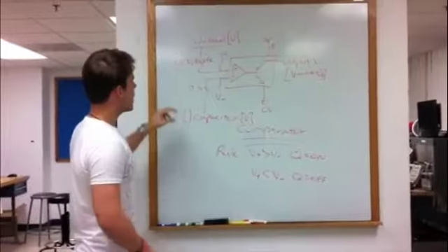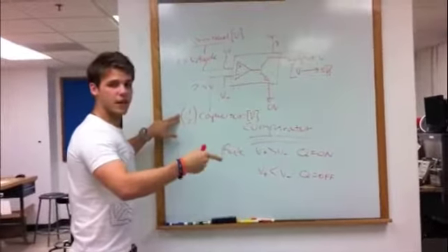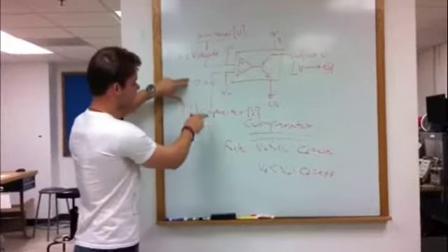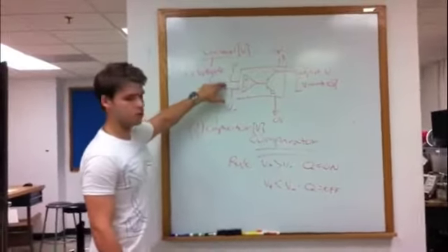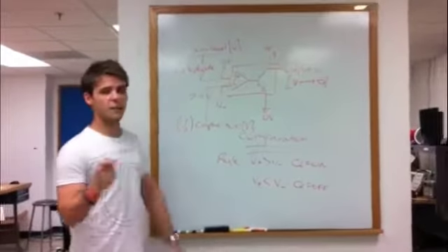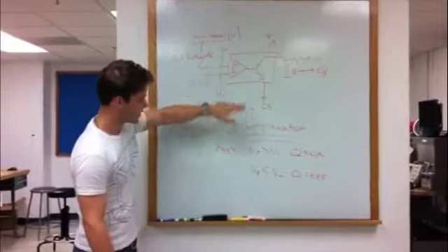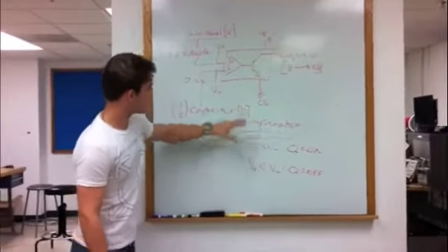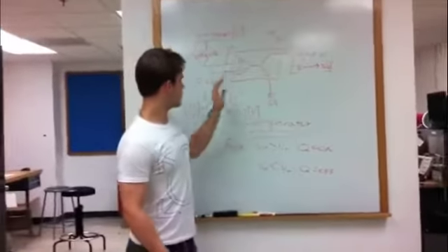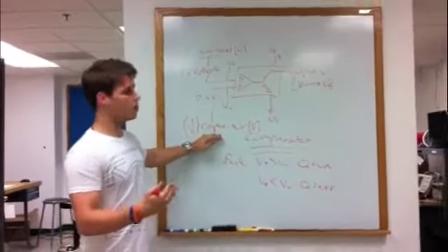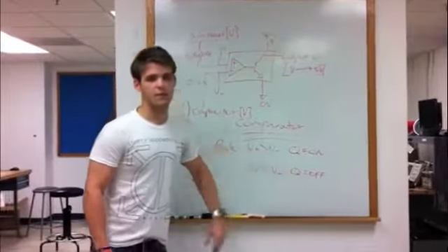We also have the solar panel charging the capacitor down here with a voltage divider in mind, so that once the capacitor is fully charged to 5 volts, this will read 2.5 volts as well. But if the capacitor were to go over 5 volts, V minus would be over V plus, and that can't happen. So once the capacitor is fully charged to 5 volts, this will shut off, and the output, by this rule, will be shut off.